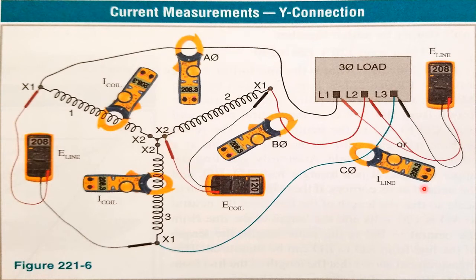Whereas the ampacity of my line, let's say I have 208 amps on line C. On winding C, I still have 208 amps. It's constant. So just knowing what's constant and what's off by the square root of 3 will help you in your calculations.